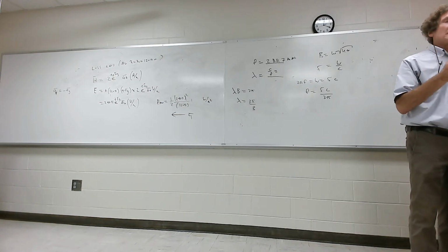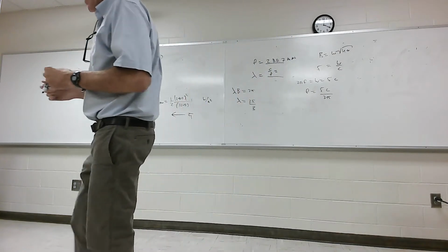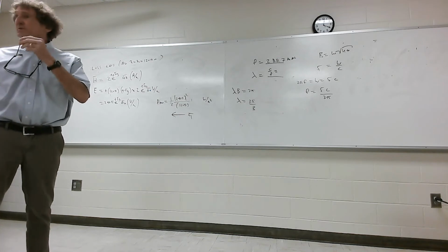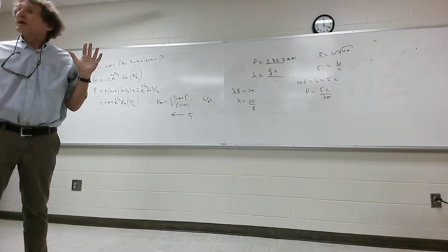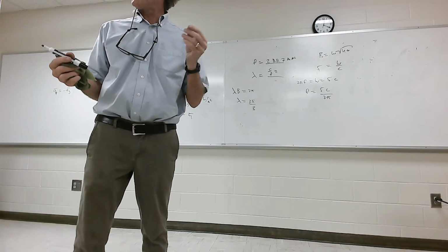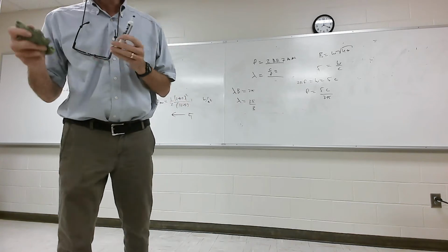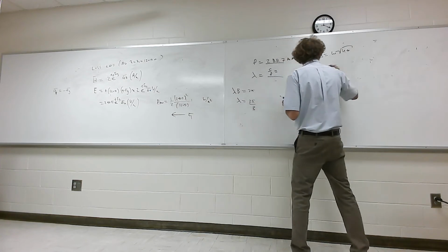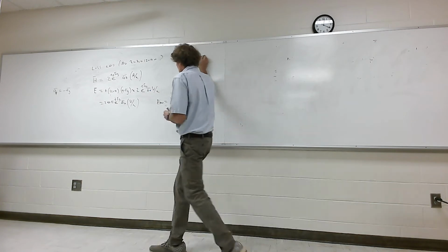Now, we did talk a little bit about shielding, but when you have a good conductor, all of a sudden things change in a big way, right? One is there's skin depth effects, correct, class? Does everybody follow me on what skin depth is? The velocity of propagation slows way down, and the intrinsic impedance becomes very small, right? So I want to just mention some of the things you have to consider for a good conductor, because we haven't really done much with this in a while.